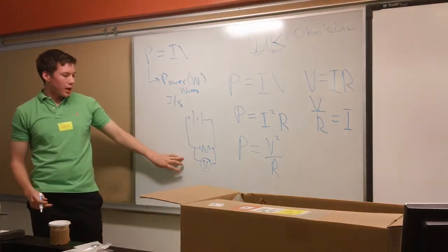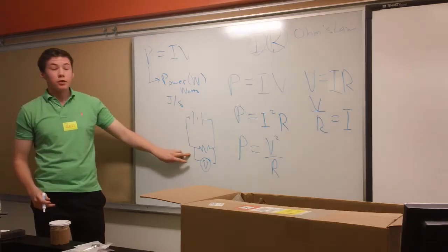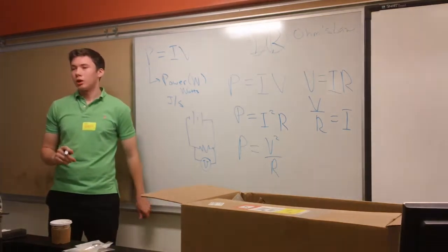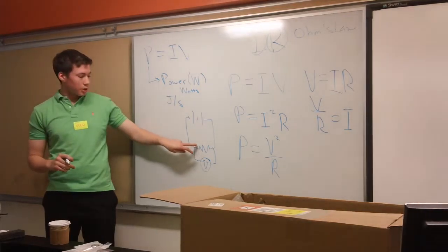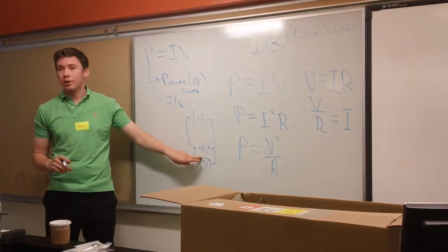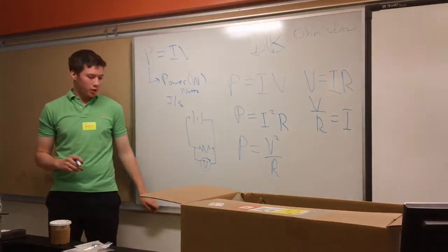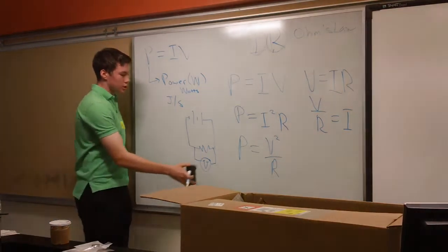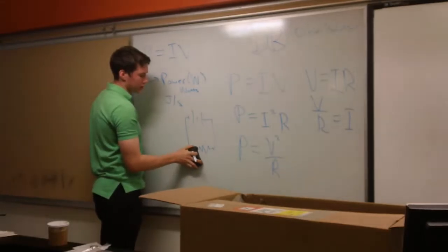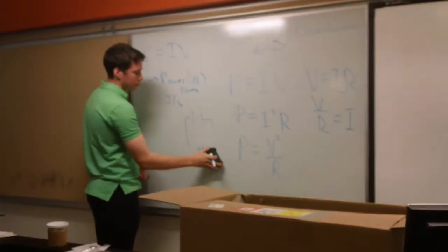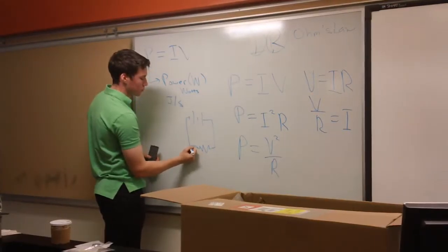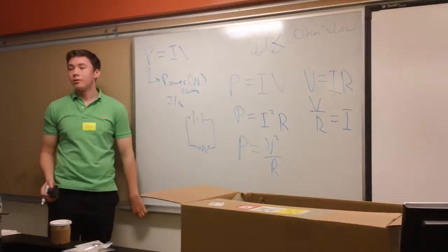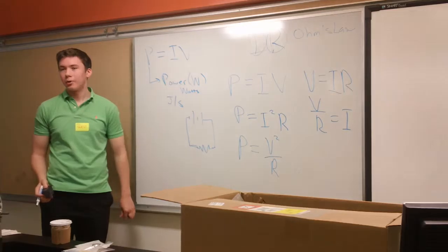So that means that even if you don't know the numbers, you can use the digital multimeter, hook it up like this, and you can find the voltage across it. What about the current? Good question. So what if I want to find the current that flows through this circuit? What should I do? Put an ammeter. Where do I put it?